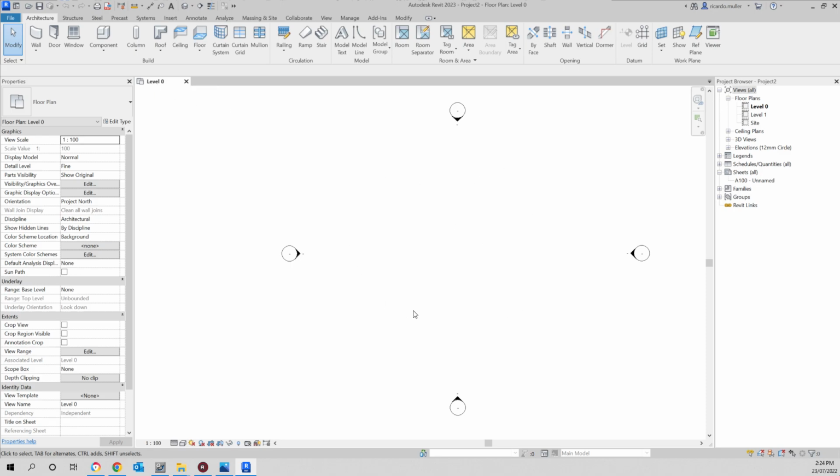Which is a plan view. Okay. Now, depending on the Revit version, it might actually come in as Level 1 from memory, but don't worry, it'll typically be a plan view like so. By pressing the middle mouse button, I can pan around my view like that, and by scrolling up or down, I can zoom in or out. Another very useful shortcut here is to press the letters Z, E to zoom to the extent of my view.